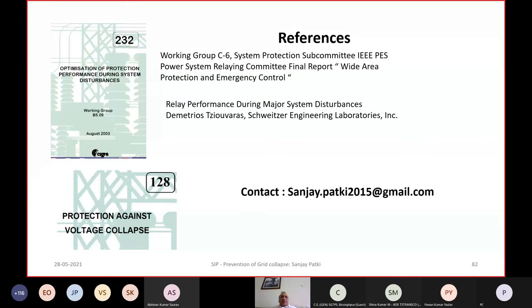In terms of special protection scheme in case of such overload, again there was inadequate load shedding because it was only by local action. So the special protection scheme will have to be treated like a more wide area scheme, where even remote load shedding should be able to relieve the overload on the line. So that is the comment which I would like to convey, because this is already there in the public domain.